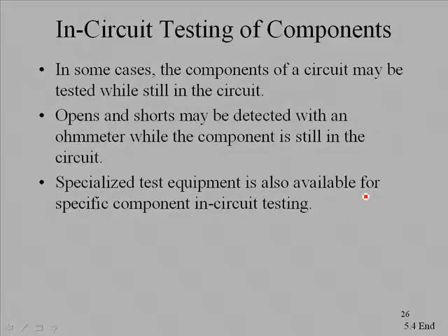components in circuits. This is often a tricky thing, though, because when you measure across a specific component, oftentimes that component is in parallel with other components, and so the reading that you would expect with that out of the circuit and when it's in circuit is often very different. So you have to really know what you're doing in order to do this effectively.